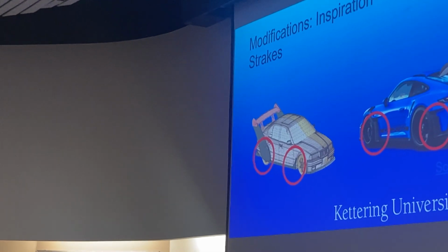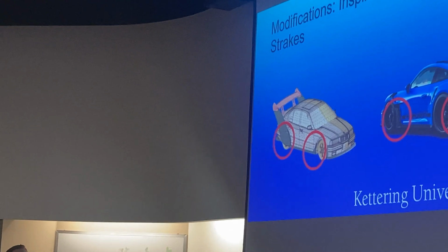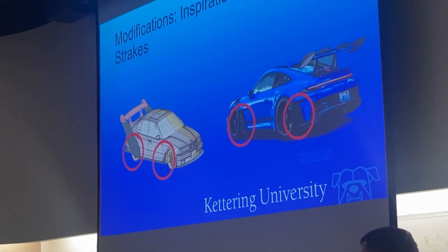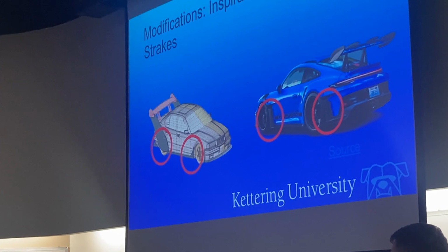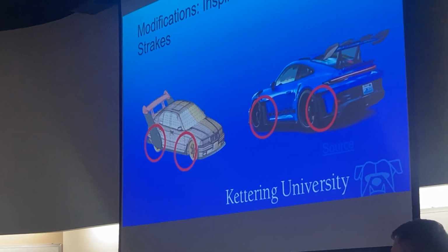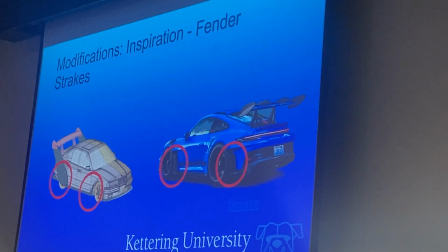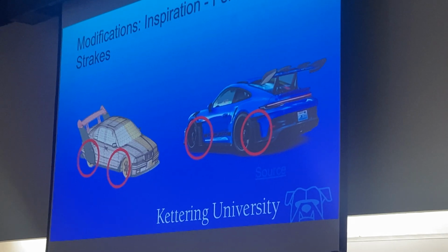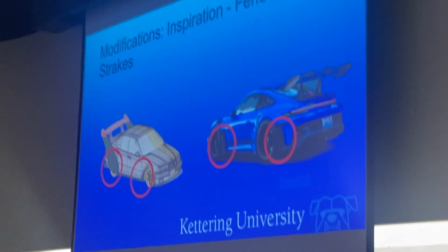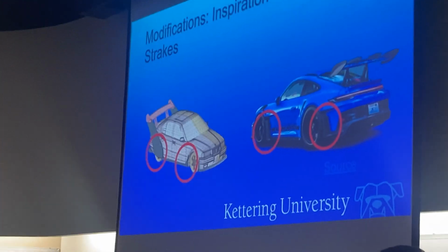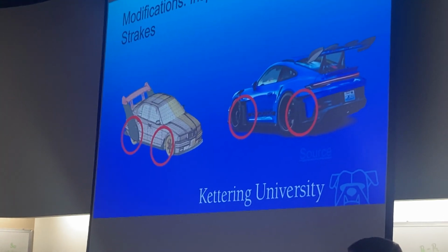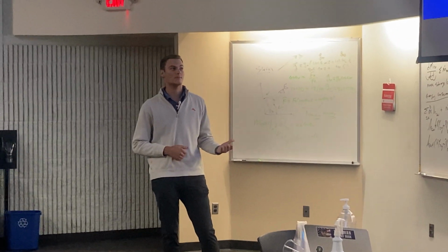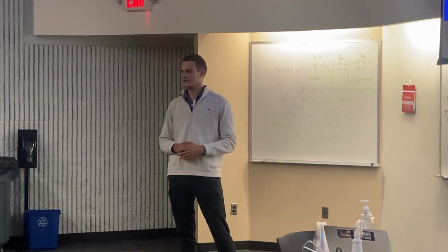And so these are our next design choice, which are the fender strakes. I cribbed it from a Porsche GT3 RS, and again, we've run into another software limitation here. It's that the turbulent air that would come off of the wheel spinning is what these look to re-streamline and reattach to the body, because the wheels will create a lot of flow separation just because they're kicking up so much turbulent air. And we can't really model this in ANSYS. So we are not able to simulate it, at least easily, with a wheel spinning to show that flow separation, but if Porsche did it, it must be good, so that's why we did it as well.